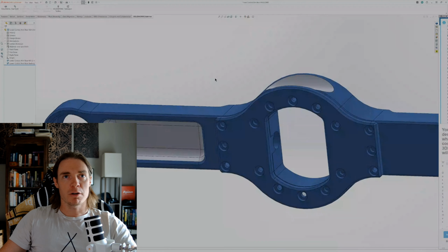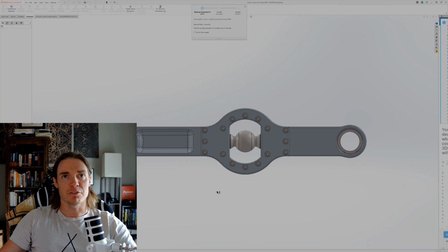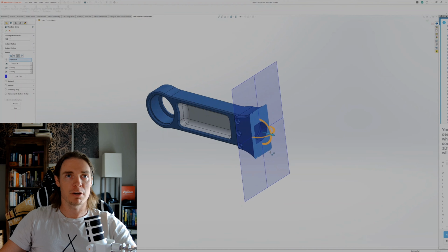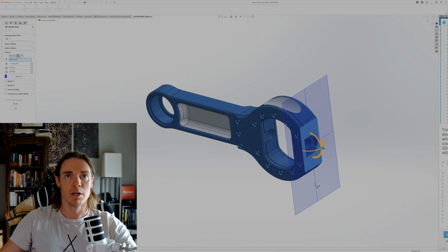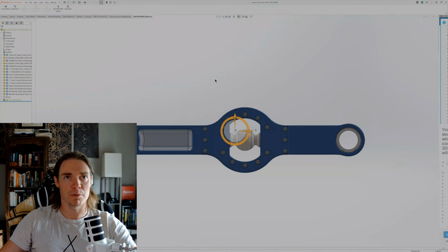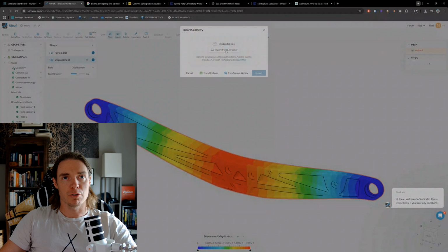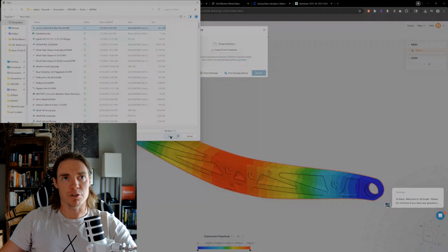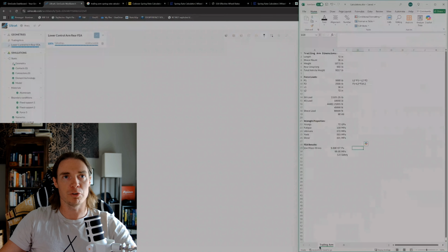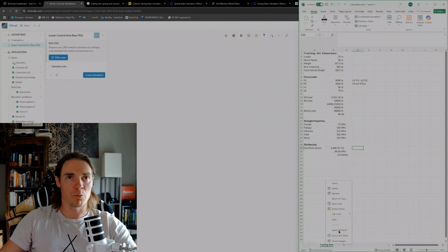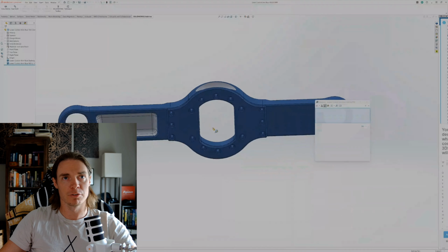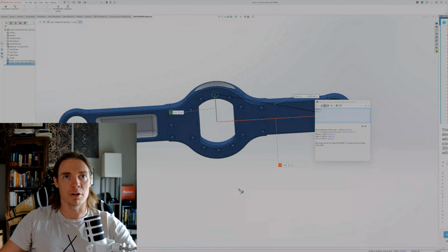So part of the shock mount was not perfectly in the center. It's offset slightly, so my force calculation ratio is going to change a little bit, but it ended up being similar. So for the purpose of this calculation, I just made it the same. So I have a 32-inch total length, 17-inch shock mount location, which gives me a ratio of around 2. And same story here, the corner weight is assumed to be 2,500 pounds, and then the shock load in the center is going to be double that.